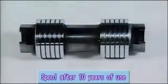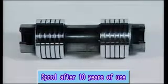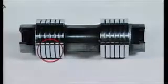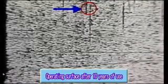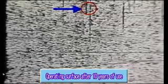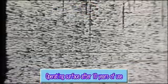We investigated the operating surface of the spool that has worked without failing using this oil 10 years after it began operation. As you can see in this microphotograph, there are no horizontal scars in the operating direction, and the vertical processing scars of when the part was new, shown at the hour, still remain. When this is compared with a new part, it is easy to see that there is extremely little friction and it has a smooth operating surface.